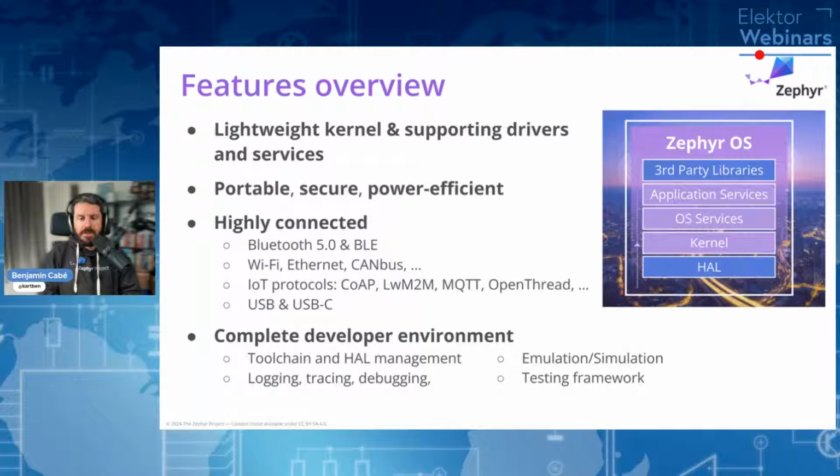For another sensor, for which the driver was written by someone else, maybe the API is going to be get TMP, something like that, which means that your code, unless you do something specific, won't be adapting itself automatically whenever you want to replace the sensor. But after all, it should, because it's going to be a temperature sensor either way. So that's the kind of abstractions I mean by operating system services, and application services that are even higher level abstractions.